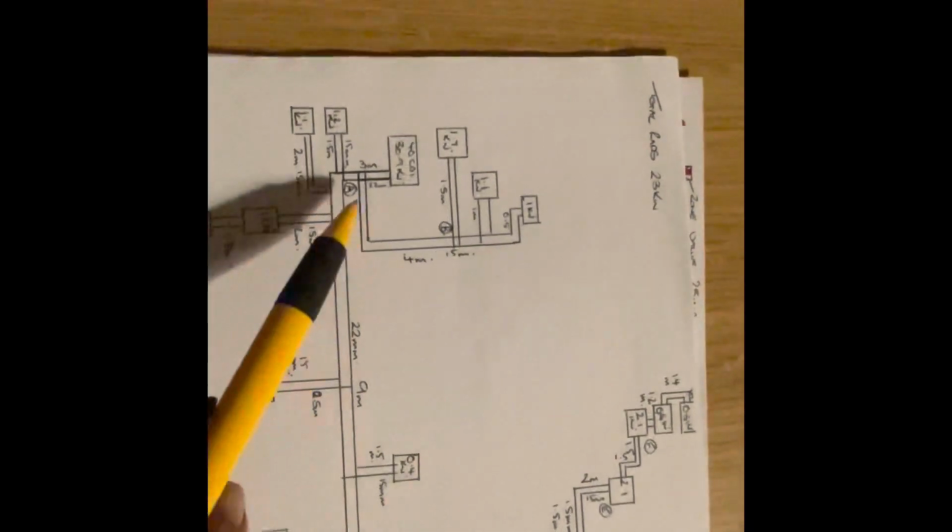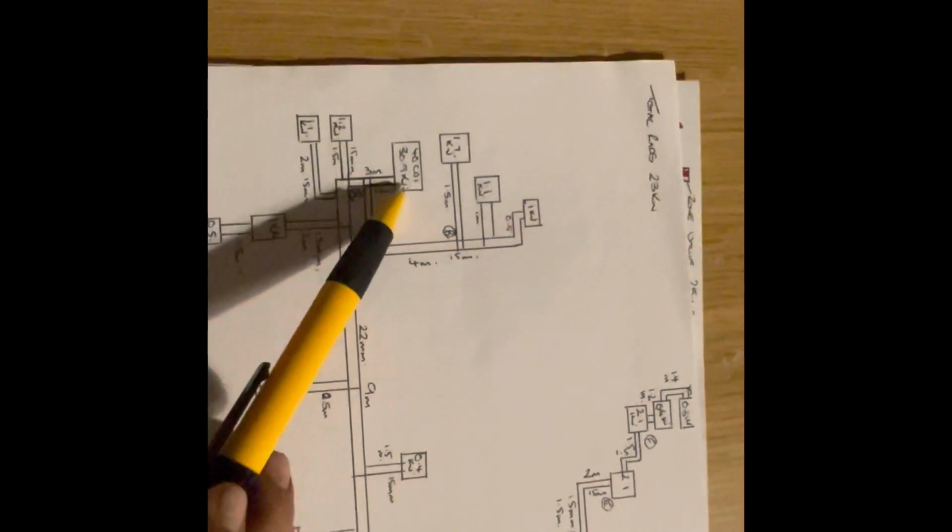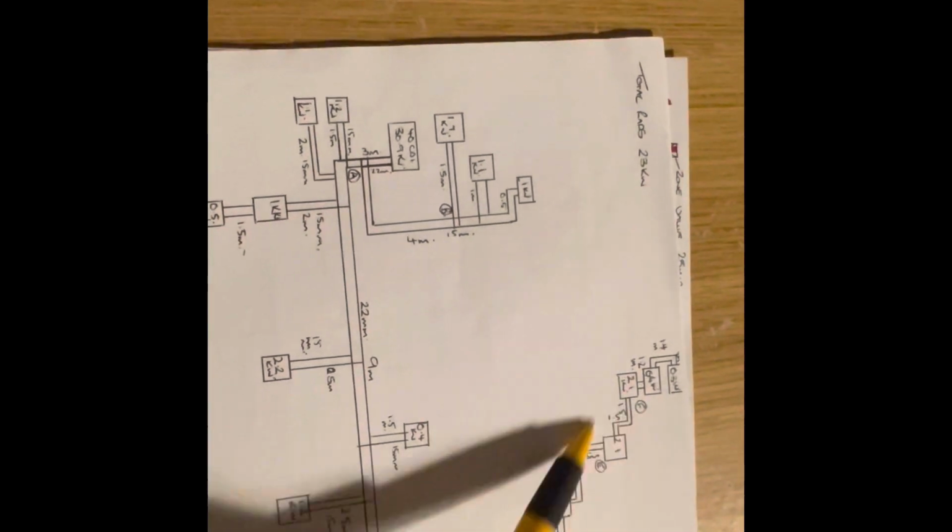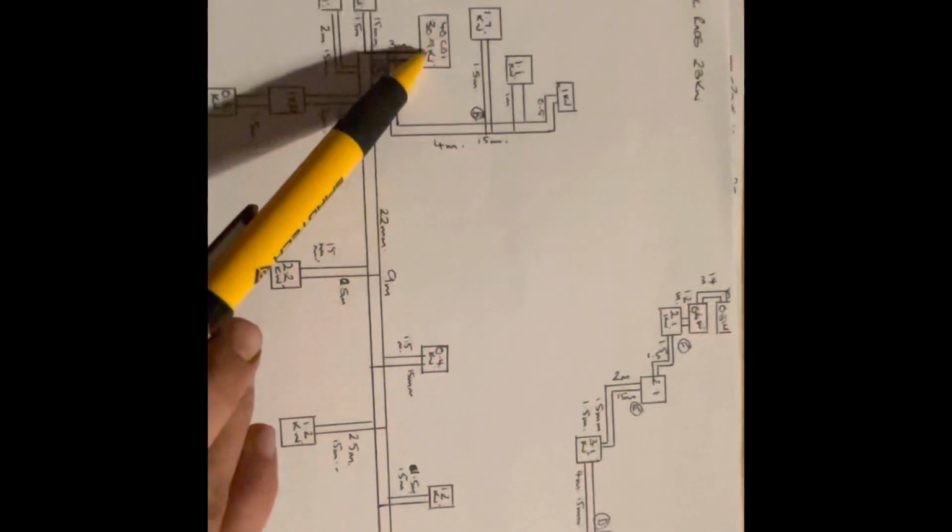Even with all these turned off, I still could not get these radiators to warm up. The reason I couldn't get it to warm up was the negative head loss on the pump and what was required from my system; my pump just wasn't up to doing it. What I've noticed a lot of installers make the mistake of is they just think 30.9 kilowatt will do the system easy.